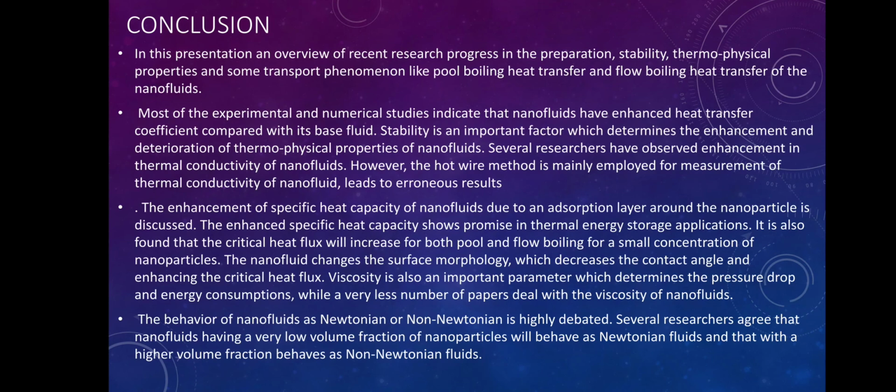While very few papers deal with the viscosity of nanofluids, the behavior of nanofluids as Newtonian or non-Newtonian is highly debated. Several researchers agree that nanofluids having a very low fraction of nanoparticles will behave as Newtonian fluids, and that those with a higher volume fraction behave as non-Newtonian fluids.